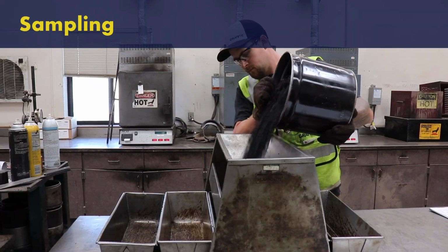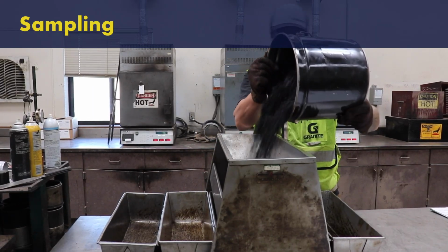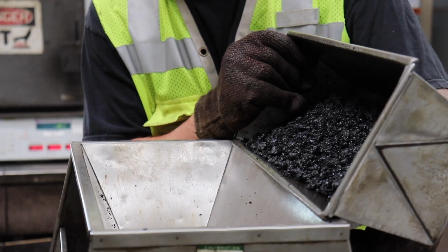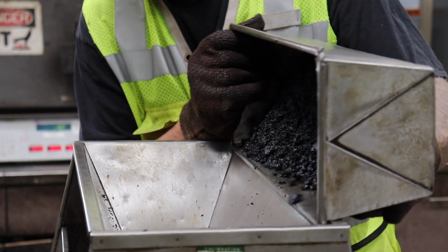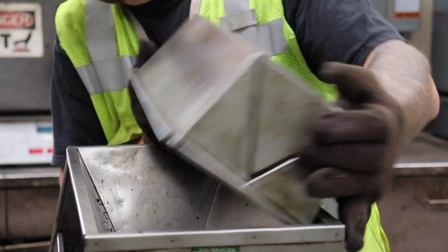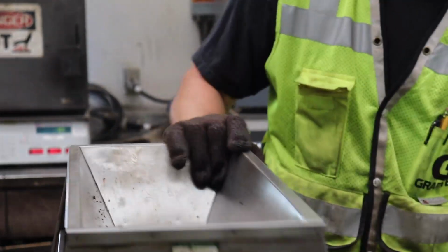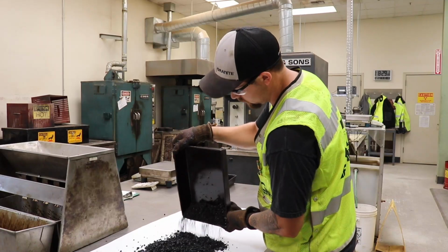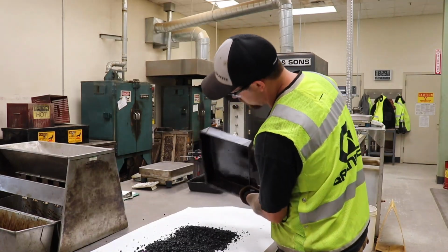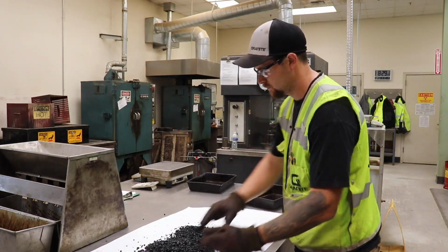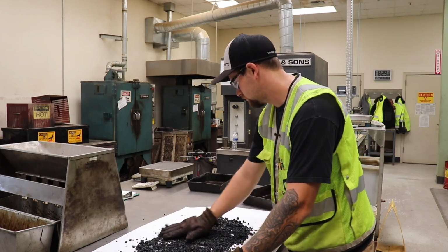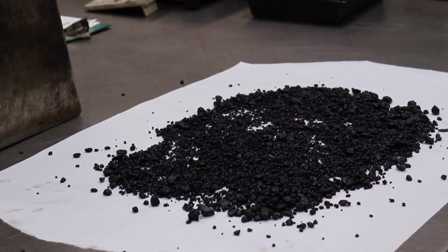Frequency of sampling and testing may vary depending on the nature of the materials, project size, and available resources. Aside from minimum specified requirements, additional sampling is recommended wherever changes in any material or its behavior are observed. Sampling during production and construction is relatively easy and inexpensive. It is rarely necessary to test every sample obtained. Use standard practices for material testing as per conventional hot mix asphalt or HMA.